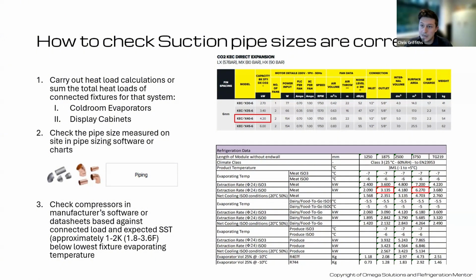From there, note down those sizes, take account of as many bends as you can, and then we'll start trying populating some software. The Danfoss one I like to use in demonstrations of these because it is free. It's accessible most places in the world, although it's very slow to do large systems.